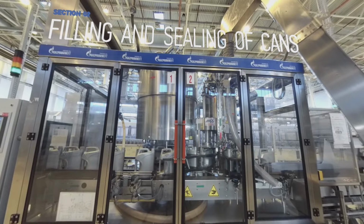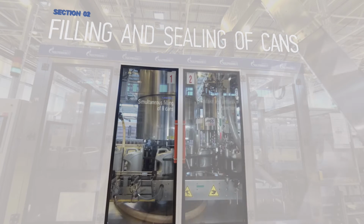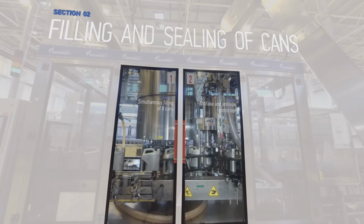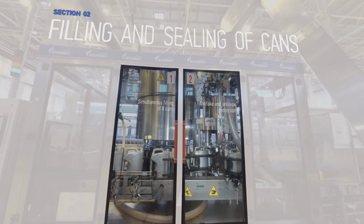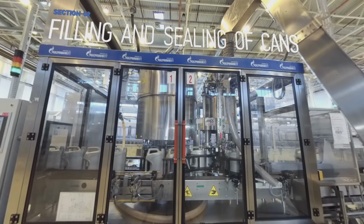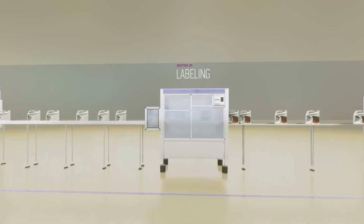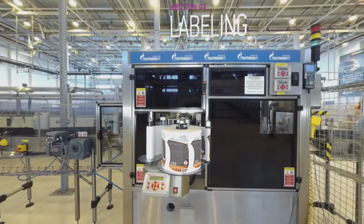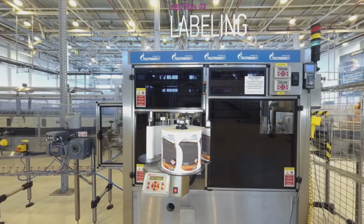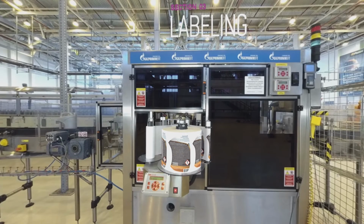After cooling, the canister is filled with lubricants in the turntable unit, and a lid is screwed onto it. The inductive sealing machine pressurizes the throat with a special purpose foil. After sealing, the canister is labeled. The laser device applies the manufacturing date and batch number.